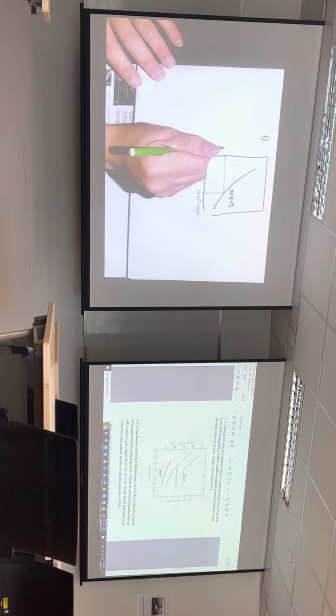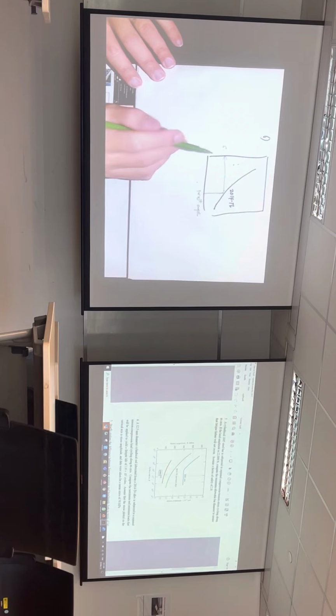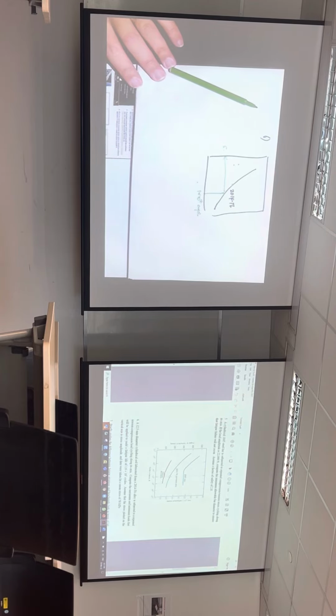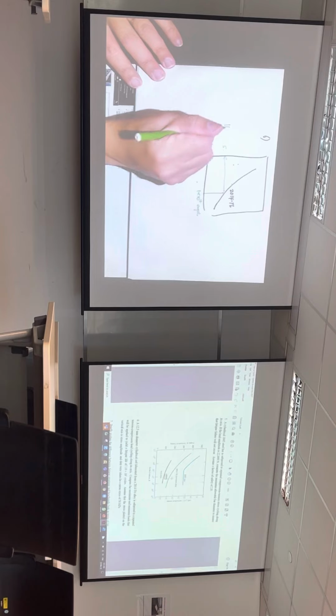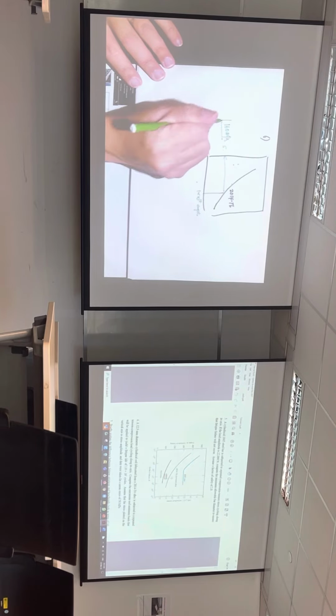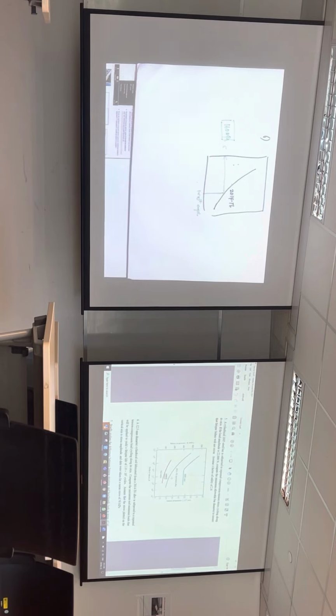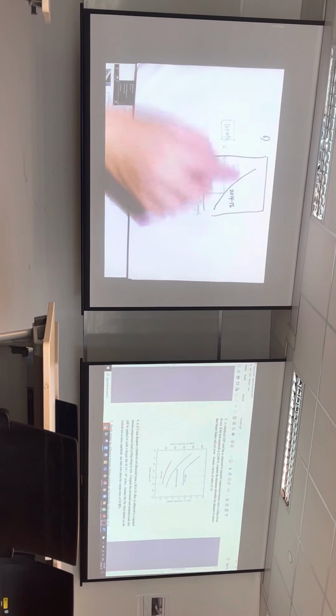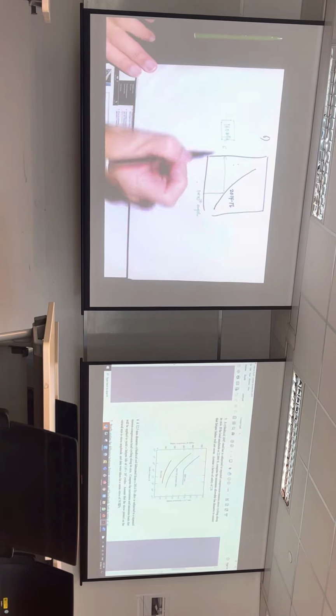This will be your stress amplitude, right? This stress amplitude, you can read some value over here. If I go to 10 to the power 7 cycles, if I read up from here, I'm probably looking at about maybe 160 MPa. So this will be my stress amplitude. Compute the maximum loads that can be applied. Assume the stress plot on the vertical axis is the amplitude and the data is taken for mean stress 150 MPa. So this thing is done on 150 MPa. So in other words, this is your stress amplitude.